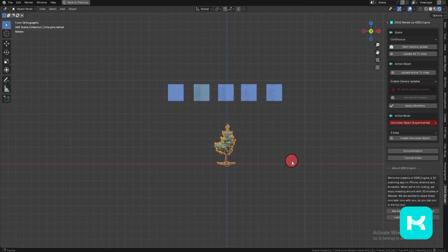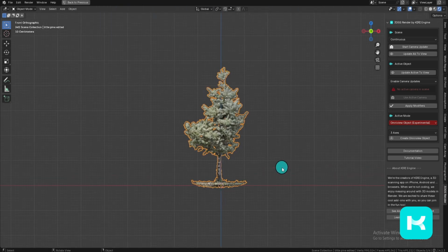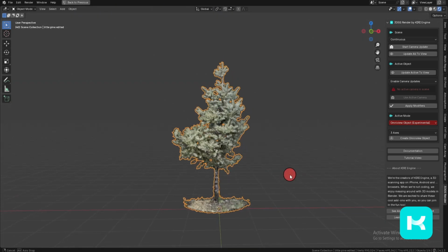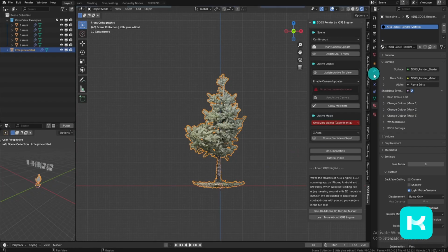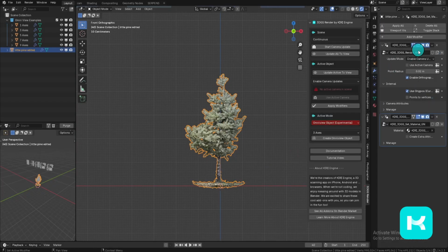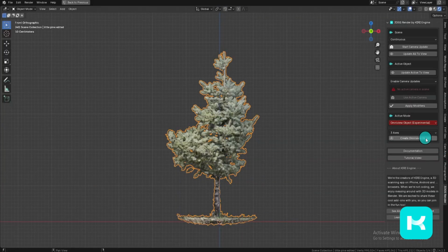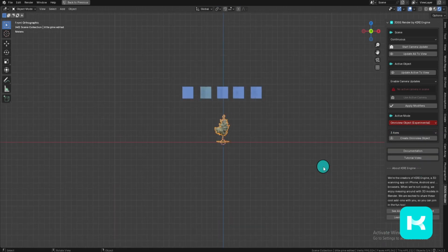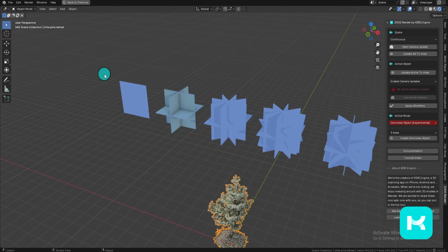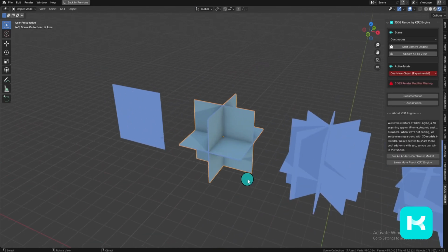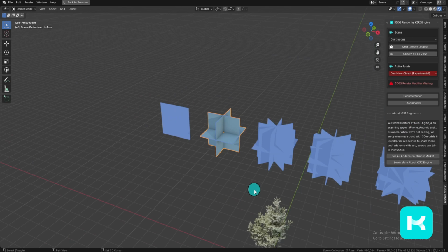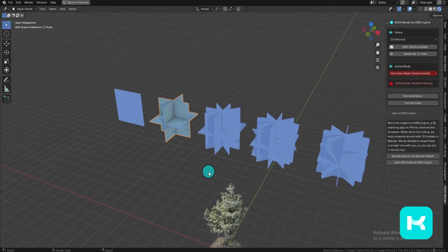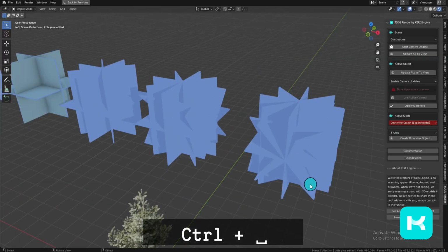To create an Omniview object, you must first select a 3dgs object that has the 3dgs render modifier attached. Once selected, the menu will let you select how many axes the generated object should be aligned to. 3 axes would create 3 faces for each point. 9 axes, 9 faces for each point.